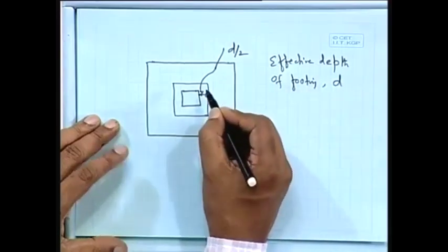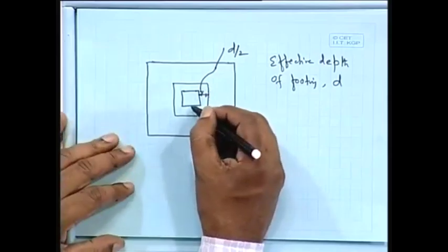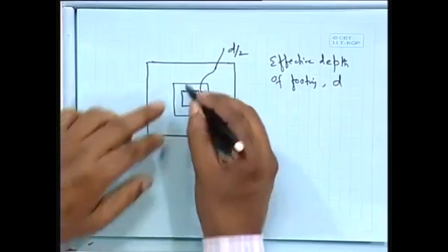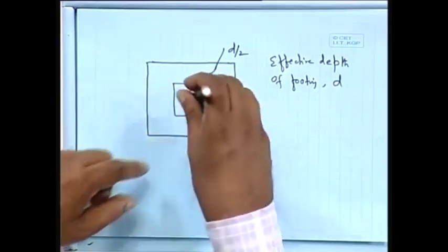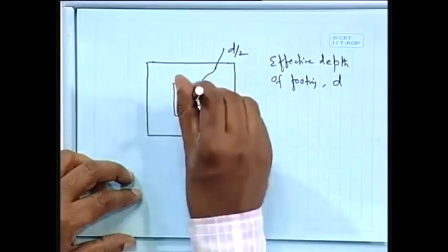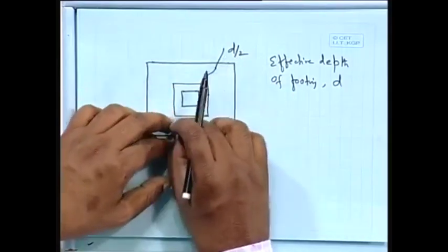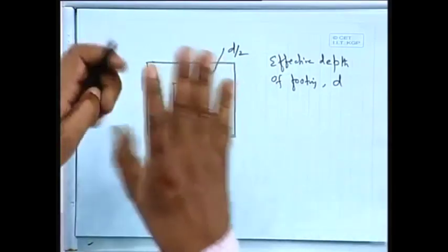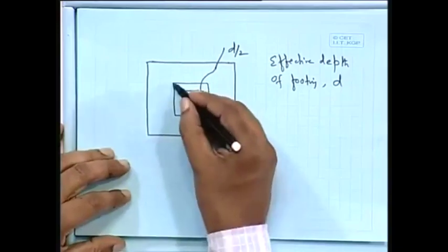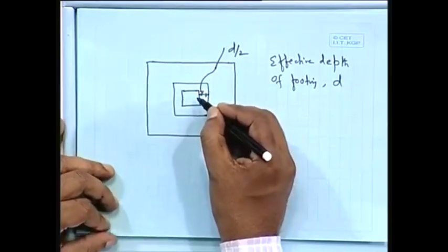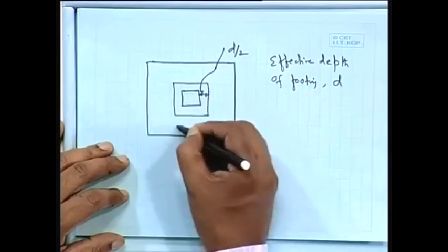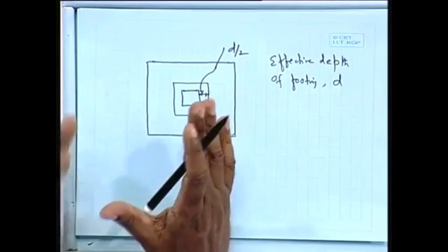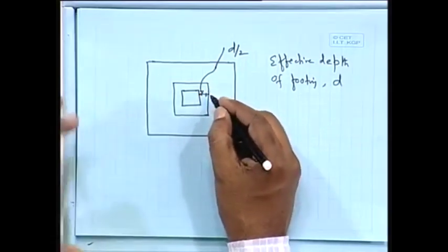What does it mean? What are we doing basically? Punching means simply it will pierce. That means as if this portion you are applying load like this, this portion will just simply break and it will just insert. You are having a plate, and you are piercing through that, and that is called the punching shear or two-way shear, or both ways, all sides you are having. So, what is the effective area? What is the area which is actually concerned with the shear?